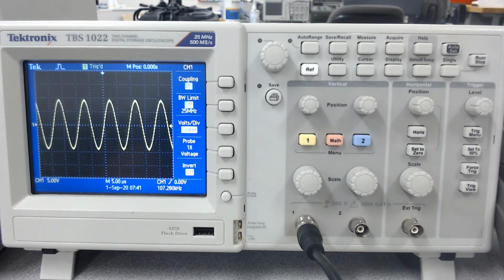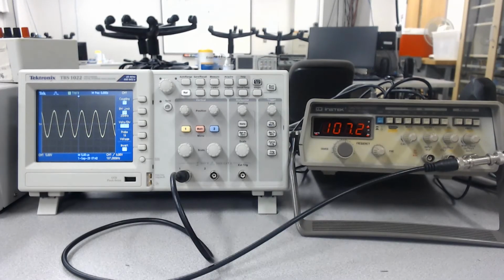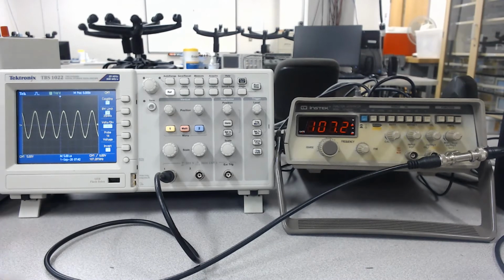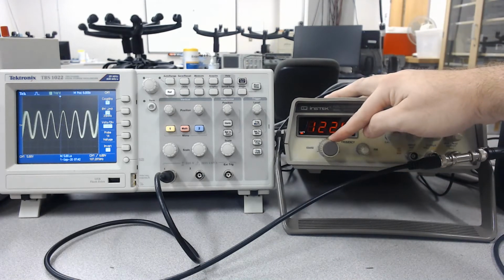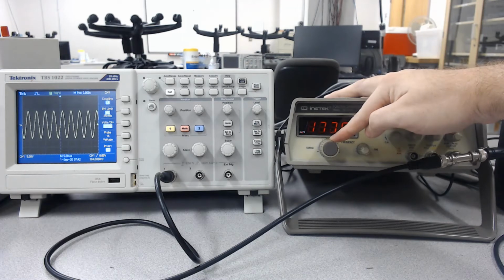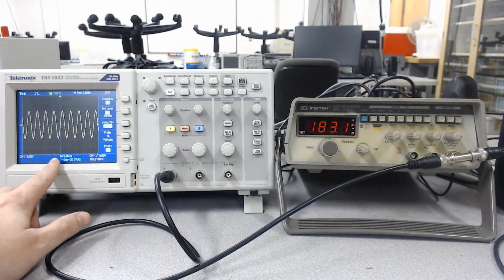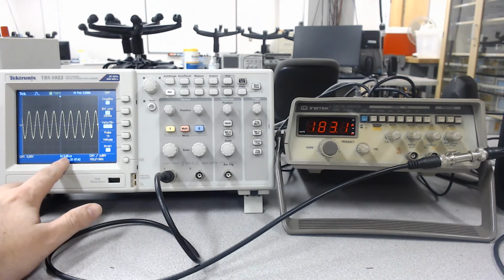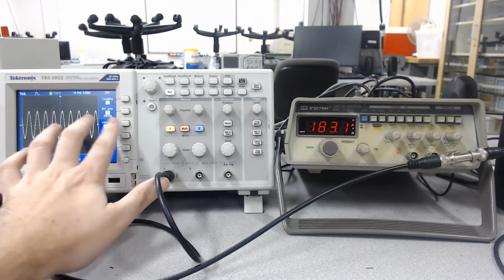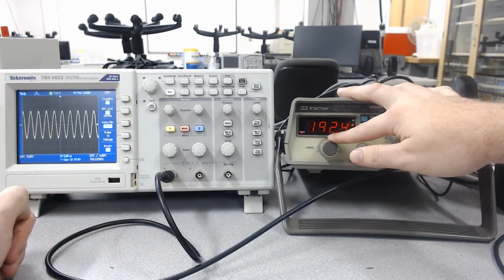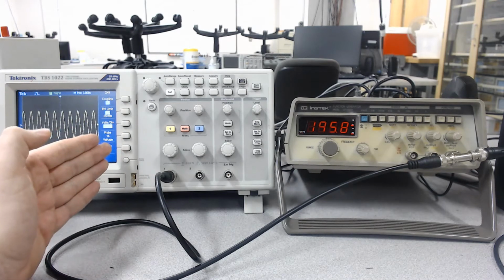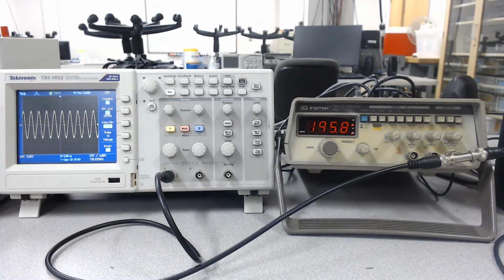Now we're going to show you a little bit farther away view so that you can see how these 2 pieces of equipment interact with each other. All right, now that we have a more zoomed out photo of this, we can see how we can adjust things. As you adjust this coarse frequency, you can see that the frequency is going up. The time frame from here to here is always the same, set by how far each division is, which you can read down here in this corner at 5 microseconds. So if you up the frequency like I've been doing, there are obviously going to be more waves in that time period, so it's getting all bunched up.